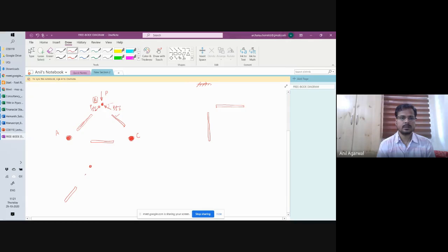So on this joint, I had found out that this force is P by root 2. Now, where is this force coming onto joint B? When we draw the free body diagram of a particular object, the object of my interest right now was this joint B. So when the force is coming onto joint B, we don't show where the force was coming from, but we have to account for it. Now, Newton's third law tells us that for every action, there is a reaction. And that reaction is on the object that was applying the action.